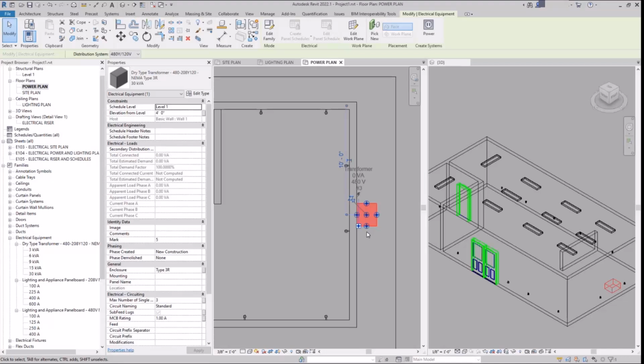Oh, 208 is also 3-phase, right? Correct. So if this wasn't 480 and it was 208, you would just do the 30,000 divided by 208, then divided by the root 3, right? So the answer is yes, but what amperage does that give you?